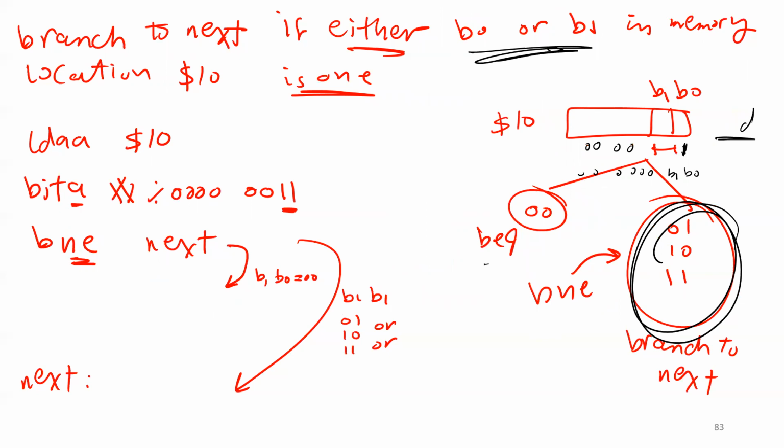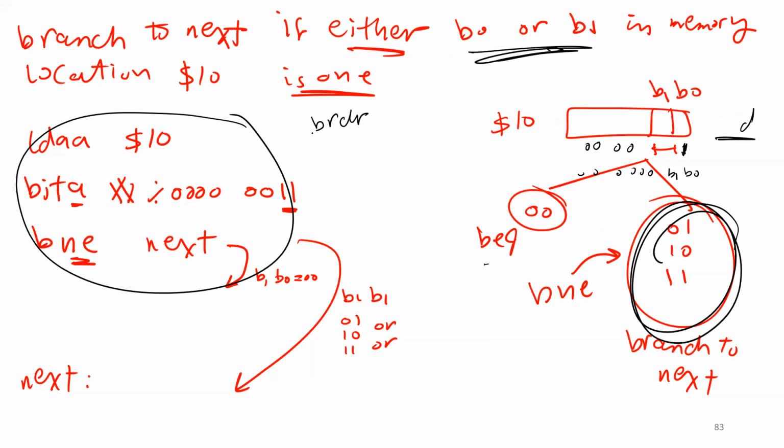If I want to do it in a different way, look what I'm going to do. I'm going to say branch if clear, if it is 0, 0. Then I'm going to say the mask is 0, 0, 0, 0, 0, 0, 1, 1, and then go to something we call out or skip, whatever you want to call it, skip.